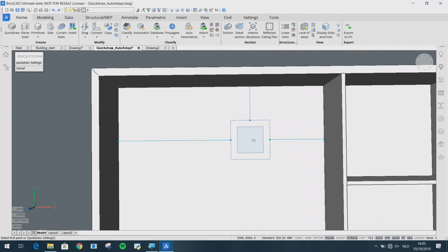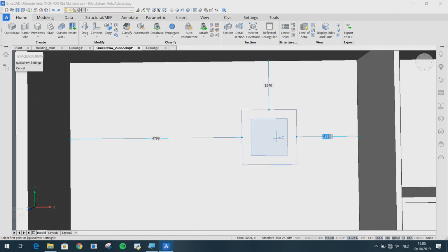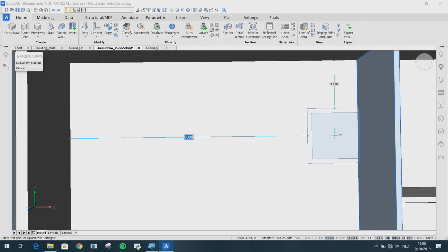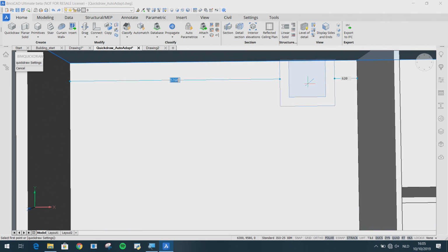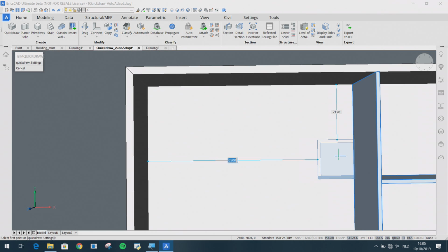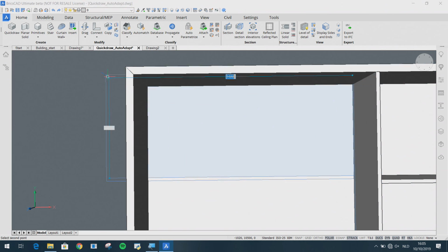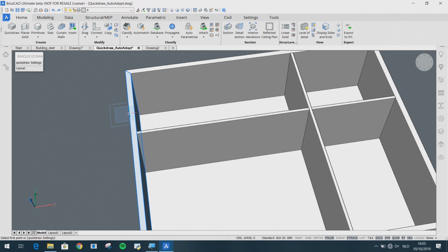So as you can see here, when Wouter moves the room cursor close to a wall that has a thickness different from the default thickness, the room cursor can adapt the wall thickness. And depending on how you approach a corner, you can choose which wall thickness you will be drawing with. This makes it very easy to work in a model with different wall thickness.